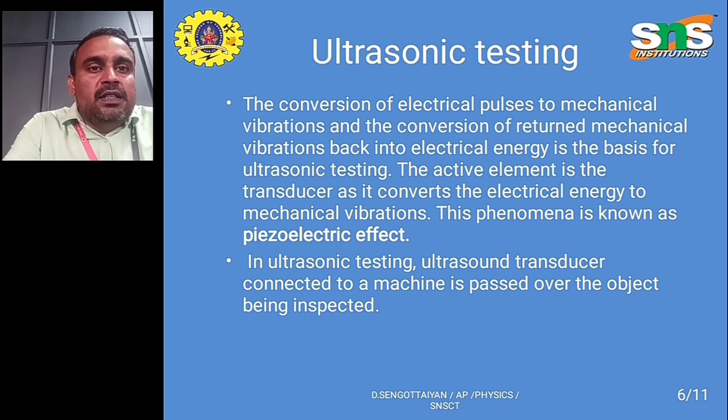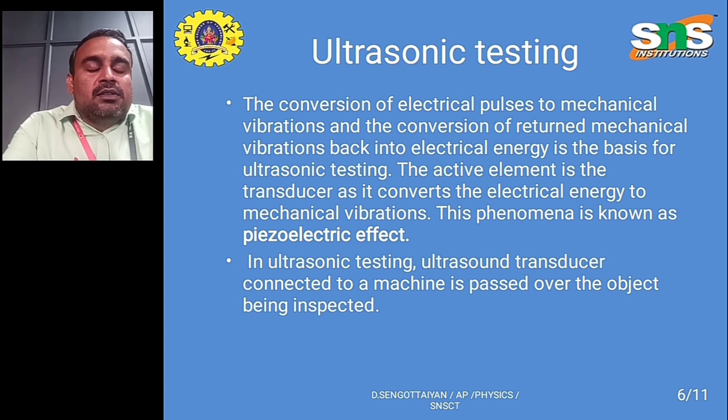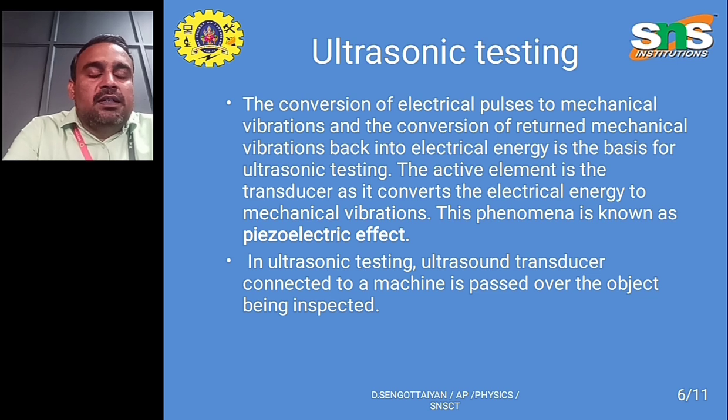The active element is the transducer. It converts the electrical energy to mechanical vibrations. This phenomenon uses the piezoelectric effect. In ultrasonic testing, an ultrasound transducer connected to a machine is passed over the object being inspected. The ultrasonic pulses are transmitted through the material, and in this way they inspect the material.